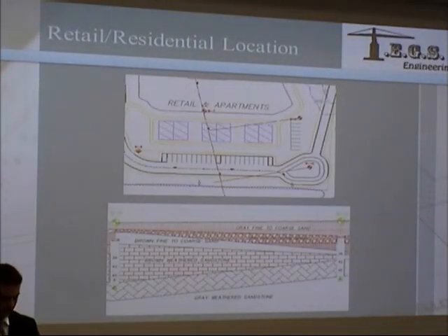The current elevation at this location is 13 feet above sea level, with a groundwater table 8 feet below the surface and a frost depth of 3.5 feet. The soils here consist of fine to coarse sand above weathered sandstone. As Kevin said before, the flood elevation is 21 feet, so the first floor will be designed at 22 feet, which will require approximately 9 feet of structural fill.